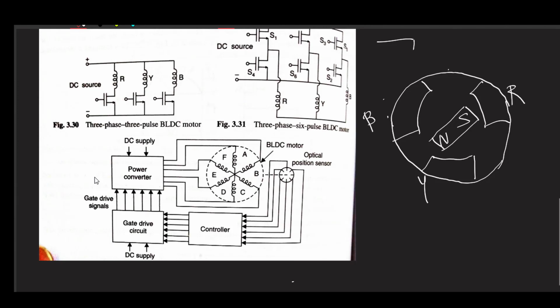Another technical disadvantage, that is, apart from the economical point of view: when a brushless DC motor is operated at low speed, then slight vibrations occur during low speed operation. Why does this vibration take place? Because there you are trying to reduce the speed of this induced EMF, the speed of this rotation, by reducing the frequency, and at that time it is difficult.